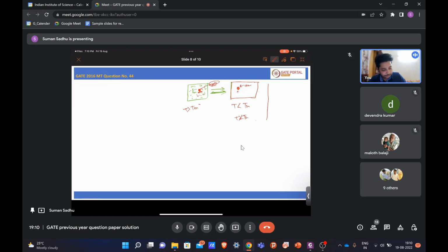And you can even find this from the delta G versus r diagram that I will show. To form a critical nucleus, or for solidification, you have these two free energy curves, one for the liquid and one for the solid. This cross section is at the melting temperature, where the difference in free energy is zero, that is, G of solid is equal to G of liquid.